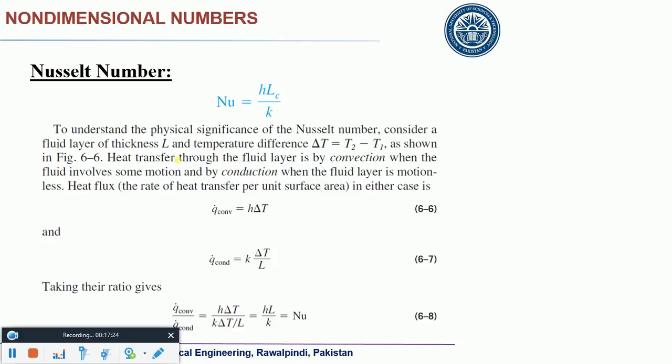So by virtue of those pi products or similarity variables, you come up with similar results if your Reynolds number remains the same, and if you talk about compressible flows, your Mach number also should remain the same. Okay, so this is the advantage: if you perform the experiments in this region of the country and someone is performing the experiments in, let's say, Europe, you know how to correlate the things. Okay, so this is the advantage.